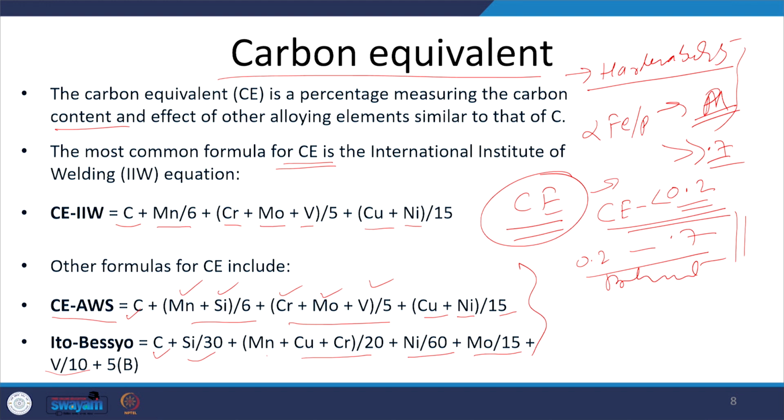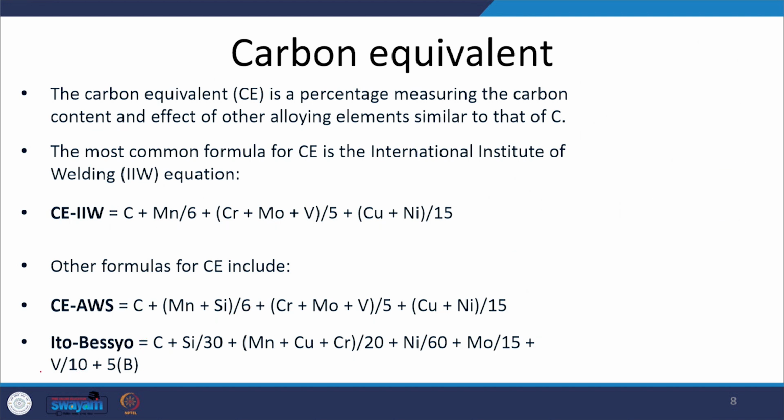Okay. In carbon steels, of course, we will be using these first two components only, where we have carbon, silicon, and manganese; other elements are the residual elements. So, ease of welding is to a great extent determined by the carbon equivalent, because the higher the carbon equivalent, the greater will be the hardening, embrittlement tendency and cracking tendency. Therefore, to avoid those tendencies, it will be required to use suitable preheat. The higher the carbon equivalent, the greater will be the preheat.